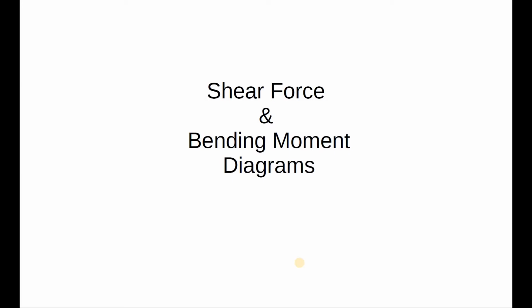Shear force and bending moment diagrams are essential to structural design, as they give occurrences and locations of maximum shear forces and bending moments within the structural elements. These maxima and minima are used to determine cross-sectional requirements for the structural elements given the type of material used. Stresses are calculated from these values and cross-sectional area is adjusted to meet the permissible stress values after applying safety factors.